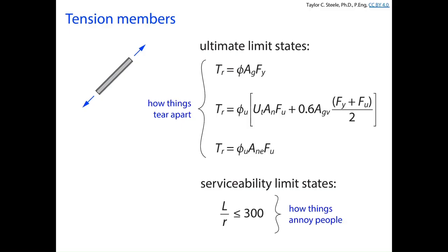If I give you a bolted connection, you're probably going to have to calculate the block shear resistance and the net section fracture resistance, considering net area after bolt holes are removed and shear lag effects are accounted for. And if there's a welded connection, there's probably some shear lag effects. If it's a welded HSS, there's some net area effects. And so you can expect to be doing these kinds of calculations on the exam on Saturday.